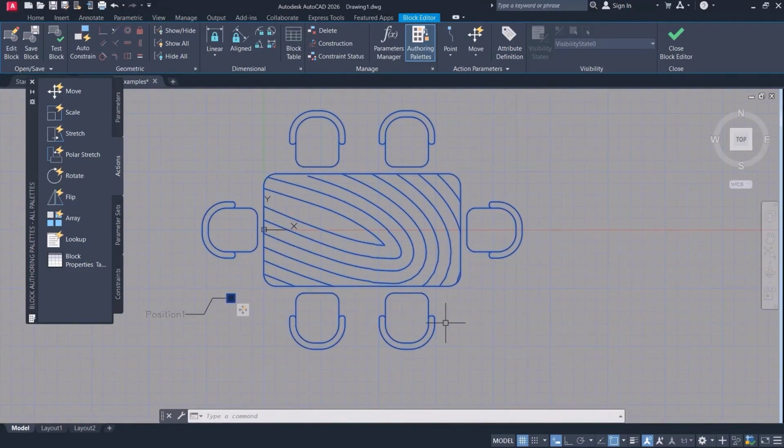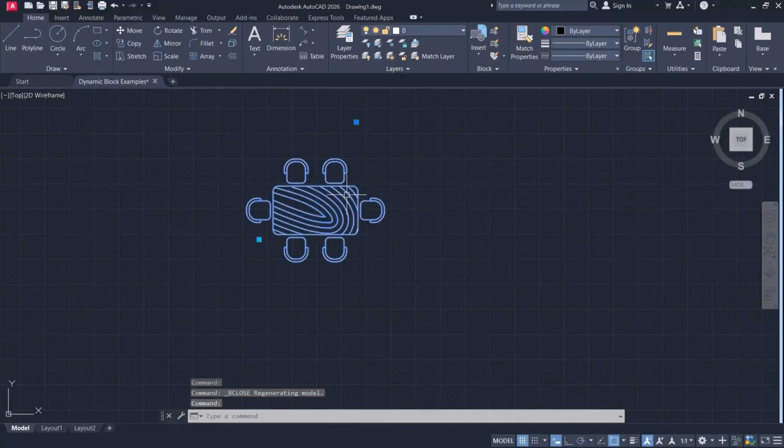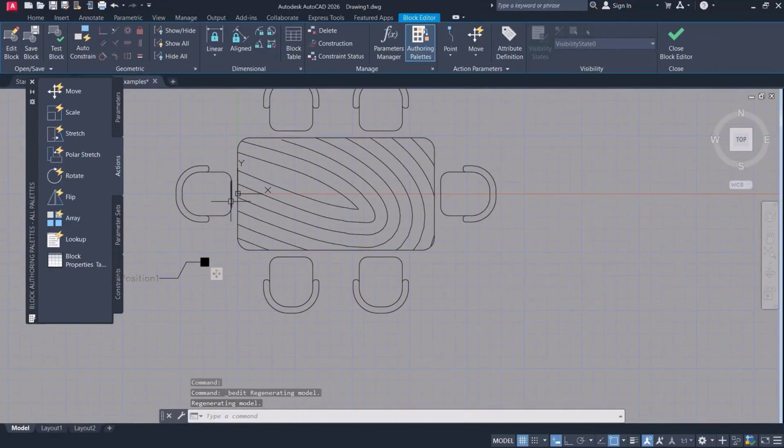Now suppose I want to be able to modify each of these chairs separately. Whether I have object blocks or I bring these in, or if they're just simple objects that I've grouped together, we've already learned how to group the chairs separately from the table. I can't modify them, whether they're blocks or groups, but I want to have this capability. I want my object to be smart. I select it and assign the point parameter to it.